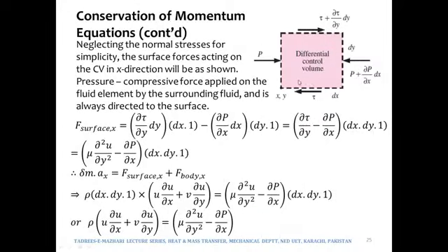So considering the surface forces, before we write the acceleration and mass over there in F is equal to ma. Over here we are being shown the two types of forces. One is the stress force and the other one is pressure. And as you already know, pressure always acts on the surface of the body. So therefore the arrows have the inward direction, onto the differential control volume.